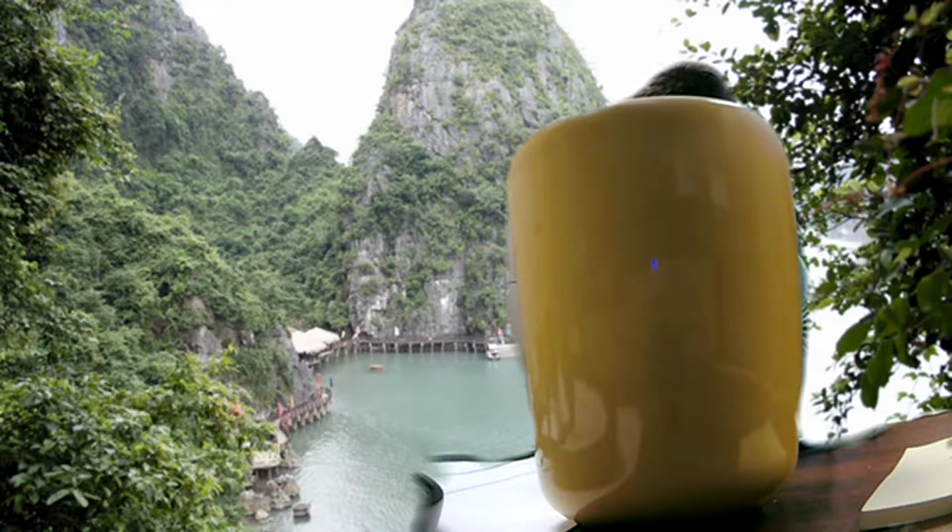Same thing up here. So we have 25% down, it's the same thing. And those are your elevations, and then on a grading plan, we just give elevations. That's all we show. It's an 8-foot wall, and then if the structural engineer wants to tier it, you say there's 8 feet of grade that needs to get up there essentially.